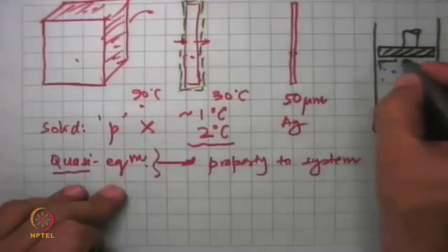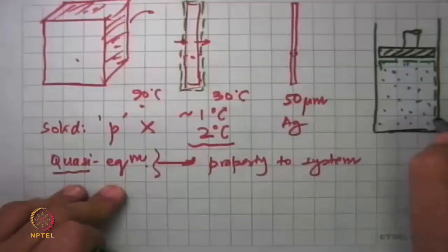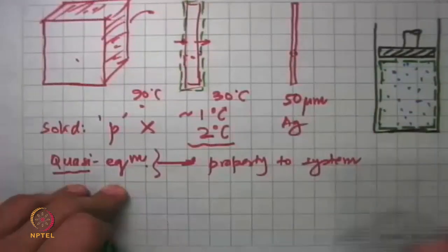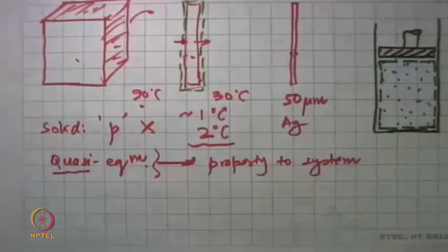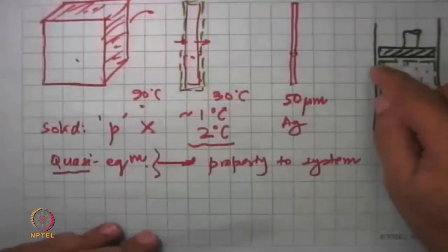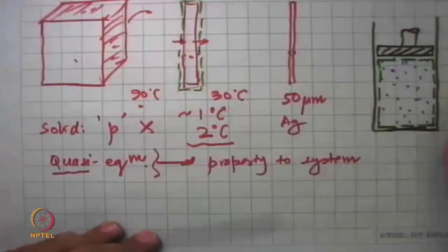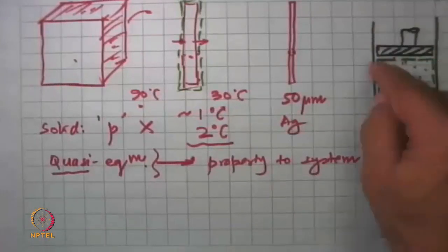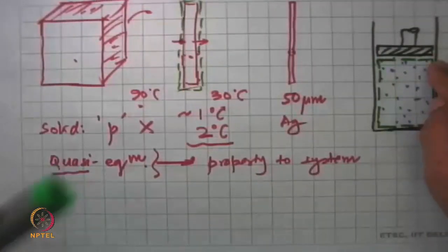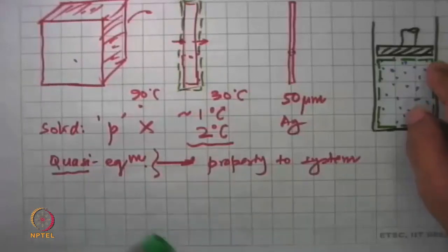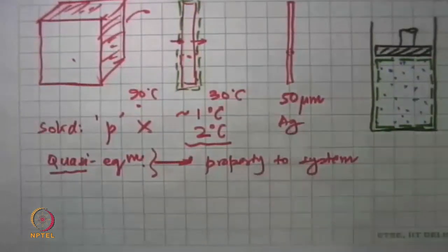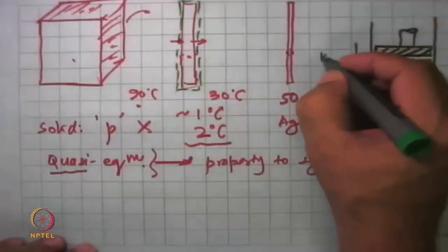And for that, we do the same thing. First, define the system boundary and say this is the system boundary, which runs along the walls of the cylinder, includes all the molecules inside it, but excludes the wall. It excludes the piston. If somebody made a boundary like this, we cannot even discuss the system. And so, very precisely drawing the system boundary and writing what's in it and what's not in it is very, very important. So that's what we've done. And we then go back and say that this piston is moving down maybe at the speed of 10 meters per second.